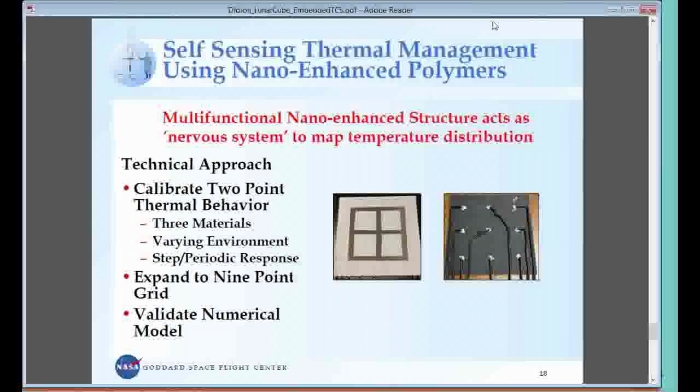The idea is, how are we going to take stress, strain, and temperature measurements without having a bunch of thermocouples and strain gauges all over the place? And I know there are all kinds of ways of doing this. What you do is you take a non-conductive material, latex paint, you add some conduction to it, carbon nanotubes, which, by the way, adding carbon nanotubes to latex paint and getting it to stay in solution is a project in and of itself. And then basically you calibrate this material and you get a coupled thermal mechanical response.